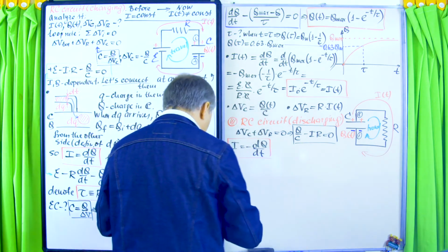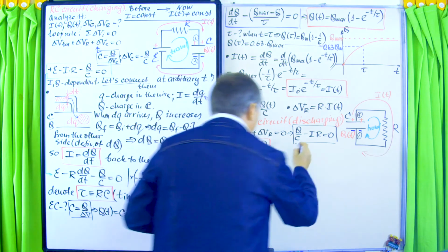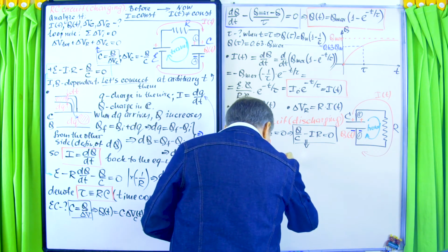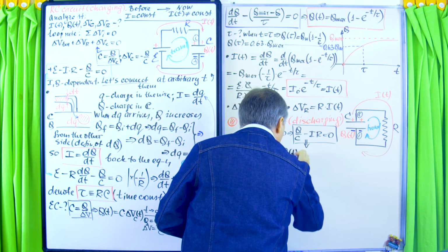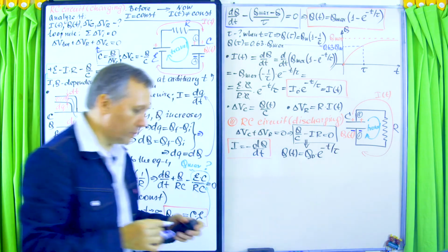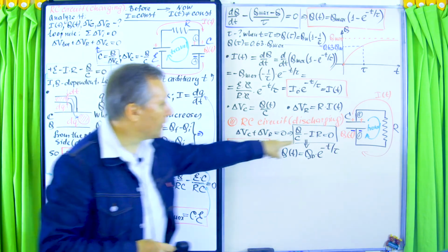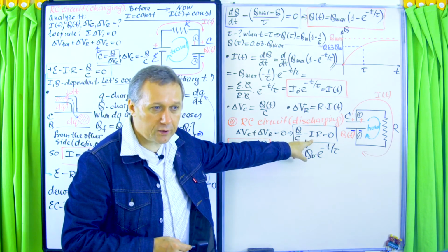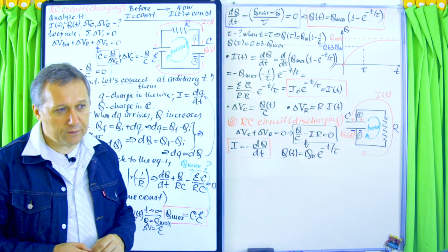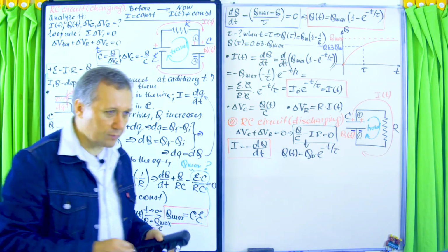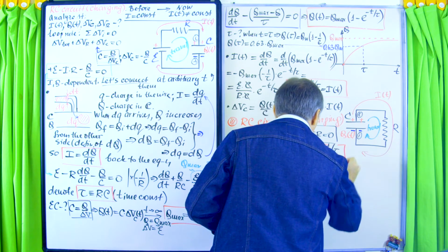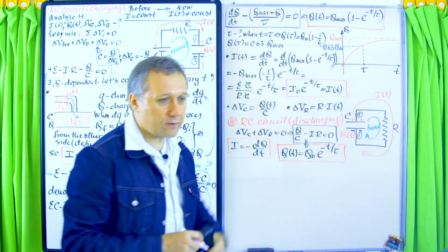Right, so then of course this can be solved for Q, right? So let me put something like this. And as a result, Q as a function of time equals Q naught e to the power of minus t over tau. So if you take this and plug it in this equation, it will be again a first order differential equation. Again, it's a very simple differential equation. For anyone who is familiar with differential equations, it shouldn't be a problem to solve it. And so that will be the function of how charge in the capacitor changes in time.